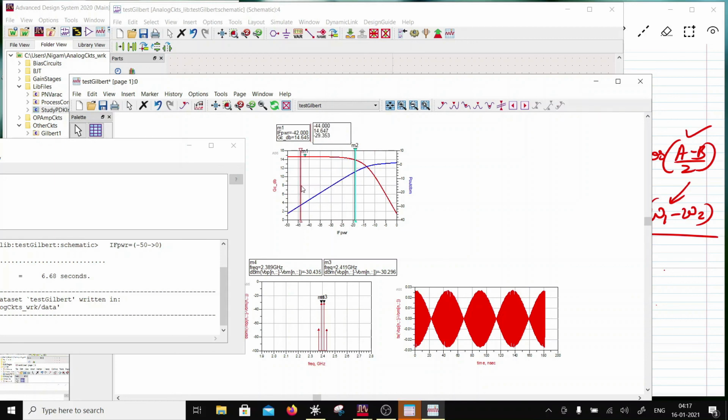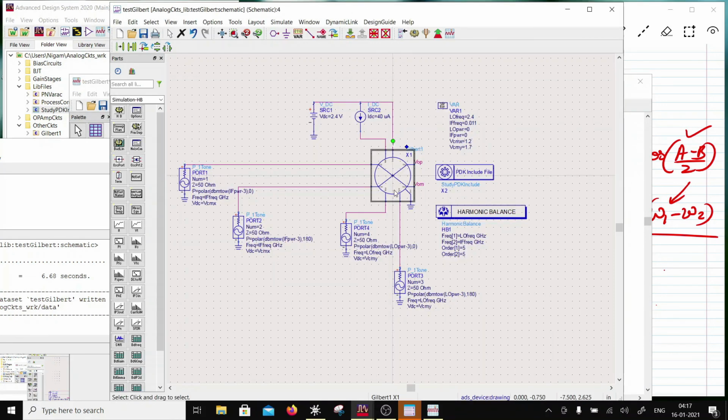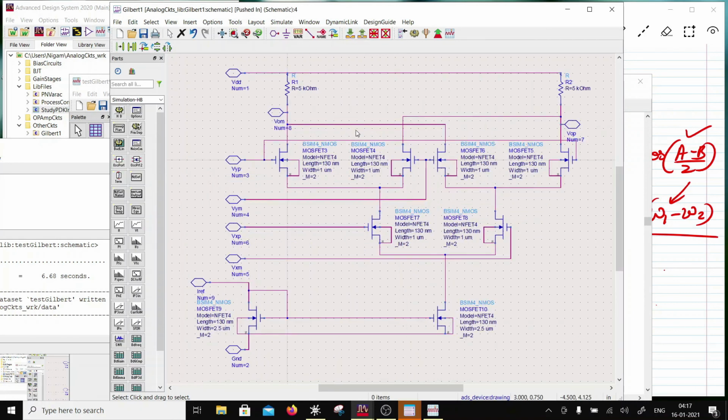So if it is over here 14.6, you are going to look at 13.6, which is over here. So it has slightly moved out, right? So the linearity will be decided by the sizing or the overdrive, and the gain will be decided by the GM, right, or K, right? So this is a session on mixer.